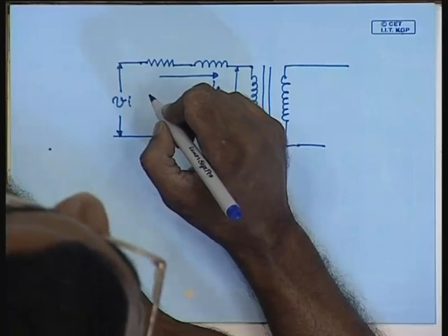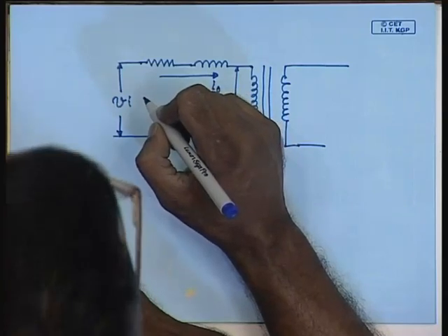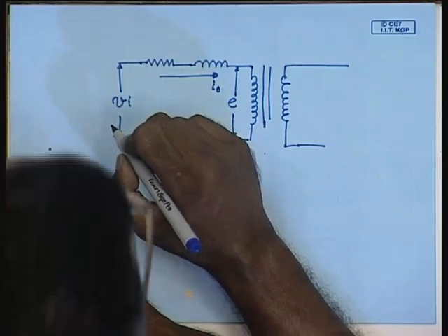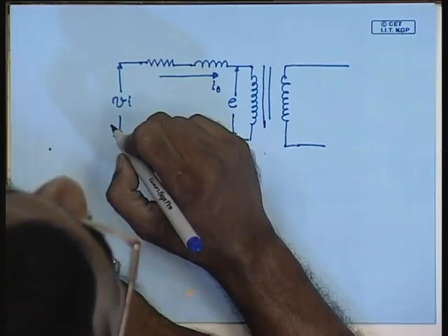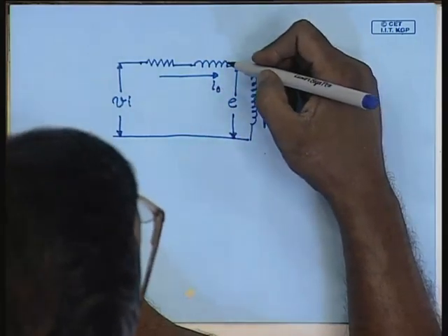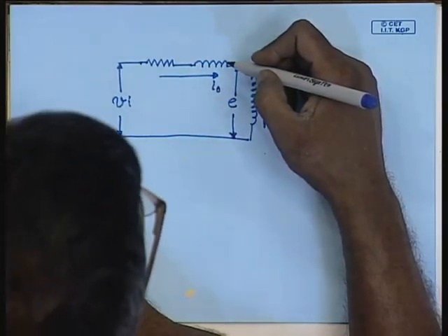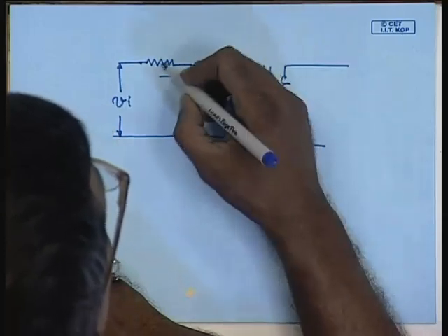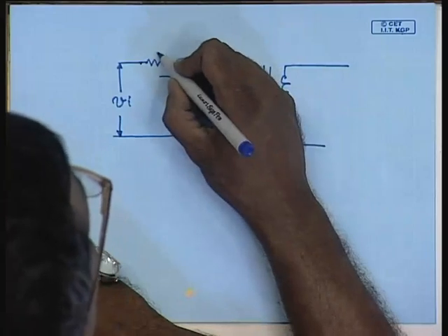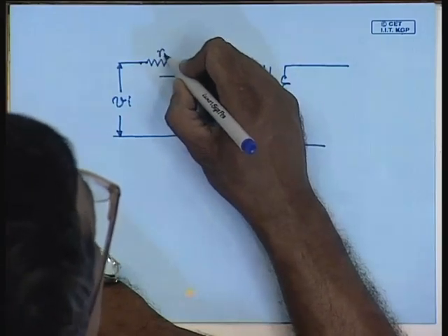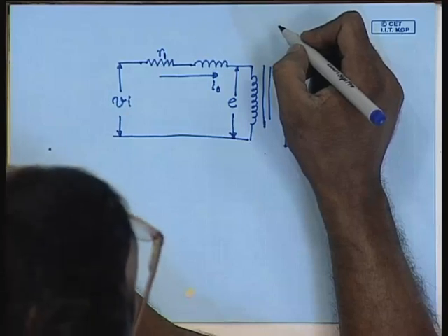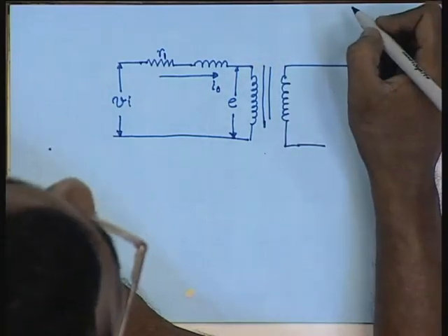Hence, even the flux waveform will possibly not be exactly a sine wave, which may or may not increase the harmonics in I0 depending on the nature of the BH characteristics. However, since I0 magnitude is very small and also the stator resistance is small, E and phi m can be for all practical purpose assumed to be sine wave.